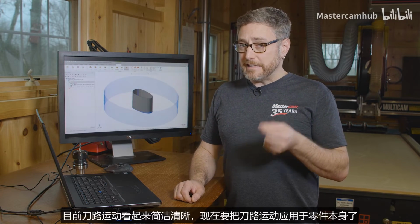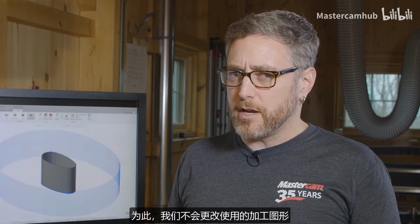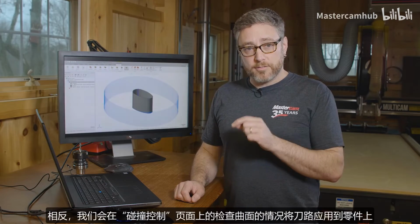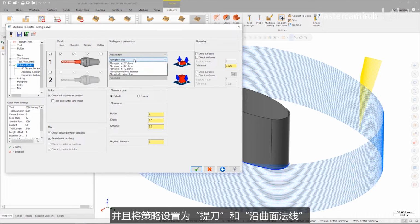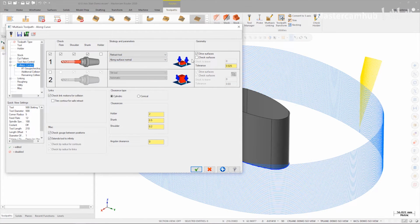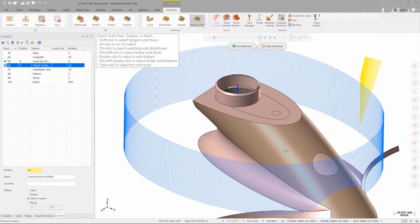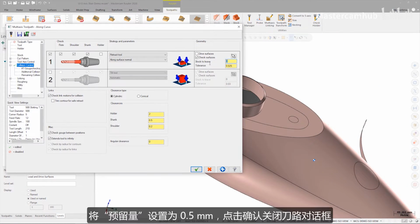Now that the toolpath has good, clean motion, it's time to apply that motion to the part itself. To do this, we're not going to change any of the drive geometry being used. Instead, we're going to use the check surfaces on the collision control page to offset the toolpath to the part itself. Now we're going to make sure that we have selected flute, shoulder, and shank, and that we set our strategy to retract tool along surface normal. Next, we'll set our check surfaces. We'll set our stock to leave at 0.5 mm and green check to close the toolpath dialog.